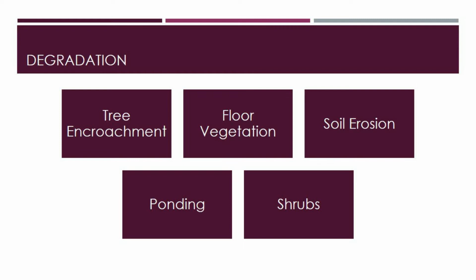Construction of ancillary buildings and structures which compromise clearances could be another form of degradation. Planting of shrubs or trees too close to pad-mounted equipment, excavations within the right-of-way compromising the minimum required clearance on top of the buried cables, and soil cave-ins resulting in damage to duct banks during construction by third parties within or near the right-of-way are the main degradation modes for underground distribution lines. In comparison to the front lot right-of-ways, the back lot right-of-ways often degrade faster over time.